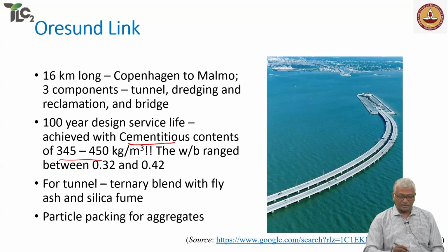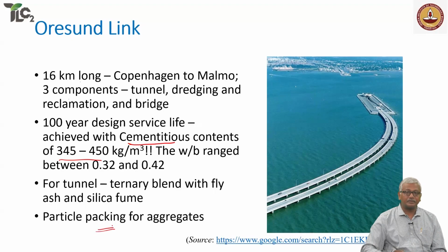They used a particle packing methodology to ensure that they can minimize the voids in the concrete, by appropriate design of the sizes of the materials that they're using. They used a ternary blended cementitious system with fly ash and silica fume, right? And with this, they were able to achieve this 100-year design life.